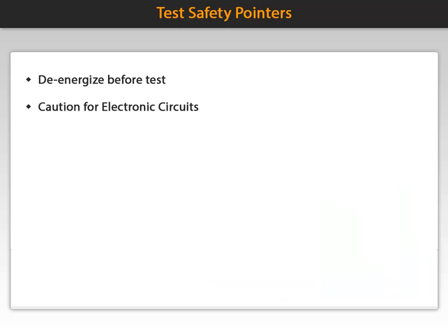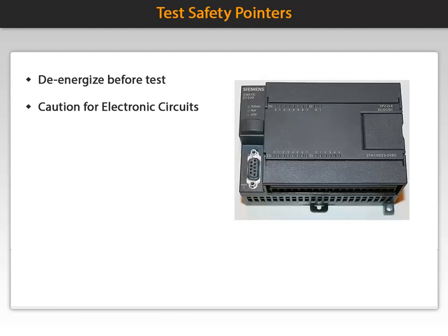The output of an insulation tester can destroy electronic circuits, which is why they should never be connected to electronic power supplies, PLCs, variable speed drives, UPS systems, battery chargers, or other solid-state devices.